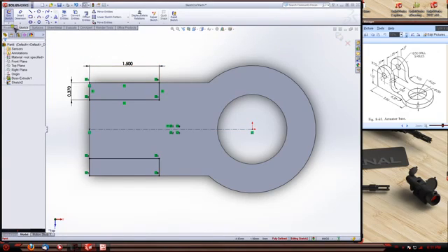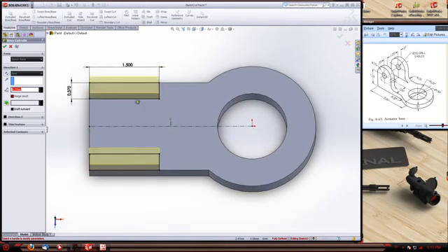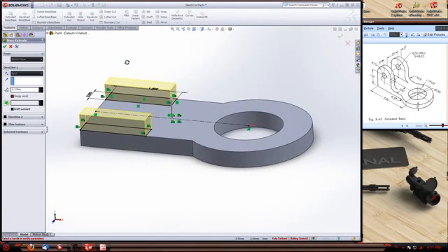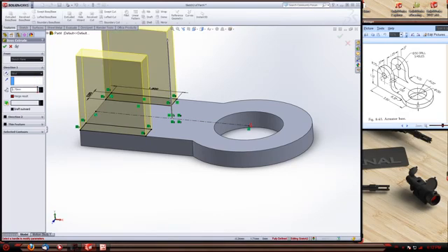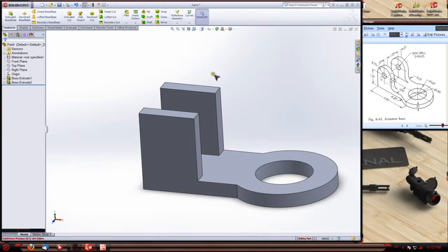Okay, now I want to extrude them, and they stand 1.75, because the plate is already 0.37, so we can subtract 0.37 off of that 1.37. Add the radius, which is 0.75, so we know that these stand 1.75 off of the base here. Hit OK. And then we're going to fillet our edges.